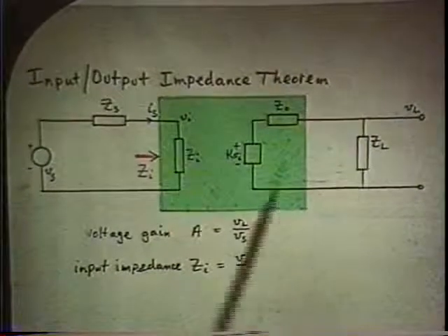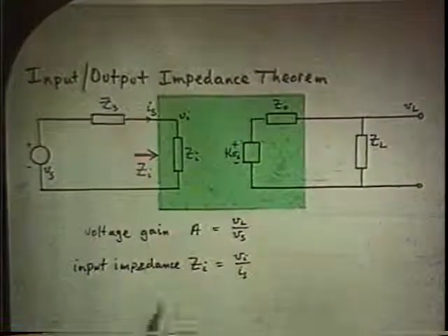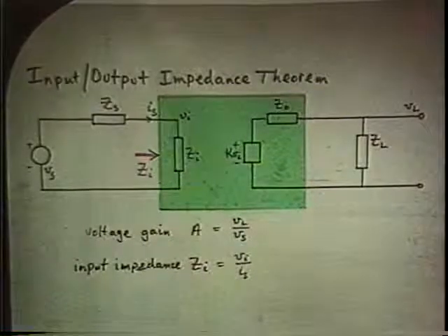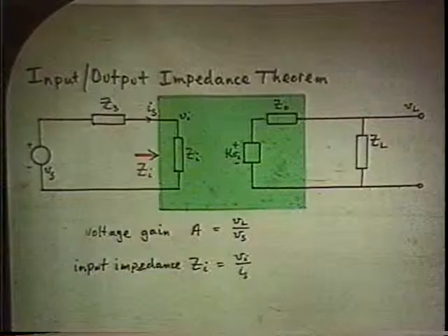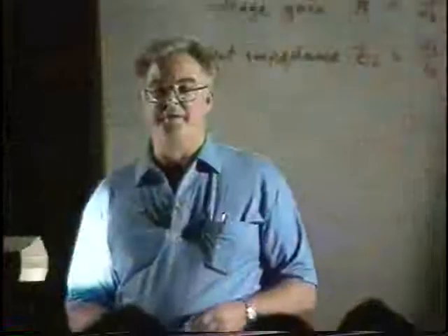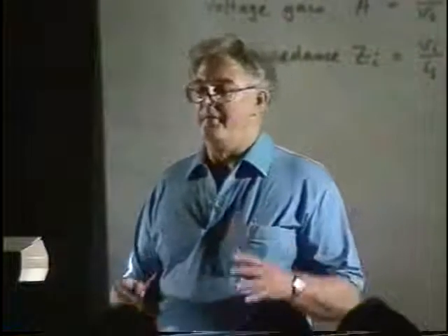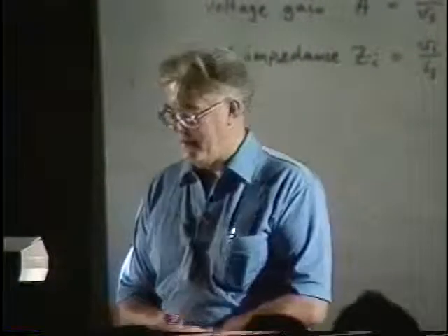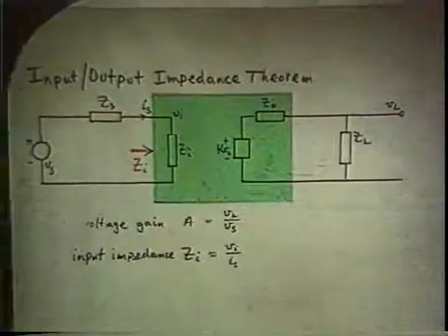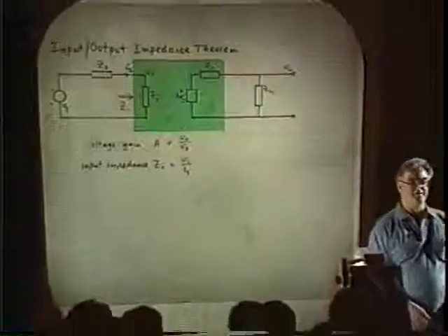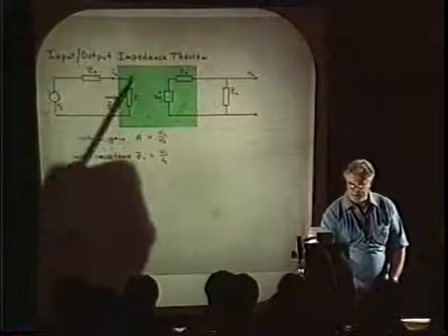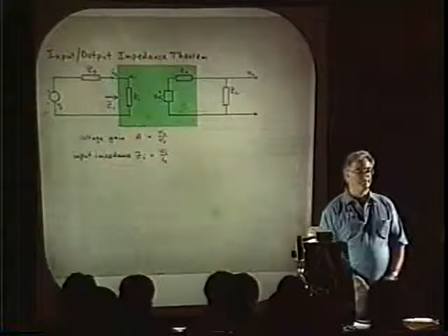And preferentially, the answer would be expressed in factored pole zero form. Okay, well and good. That's one of the specifications. But typically, there would also be specifications on the input impedance of the system. So the usual approach to the analysis is you go back to your model and you solve for the input impedance, which is a different transfer function of the same system. Because the input impedance is VI over IS.